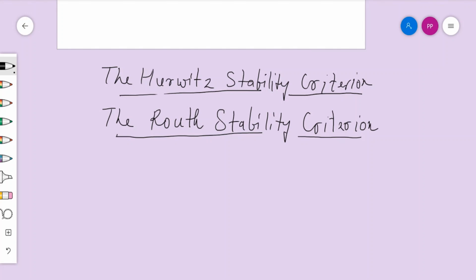So if there are certain delays in the systems, for that we have to make certain changes so that the delay, or that is the dead time, can be approximated to convert it into a system in which we can get a characteristic equation or the polynomial equation. So we shall start with determining the polynomial for a given LTI system.